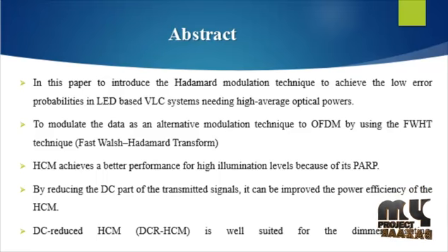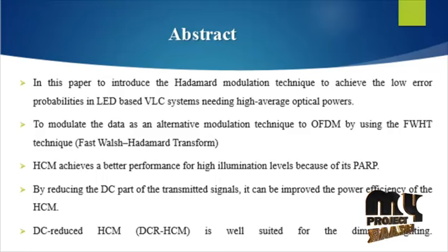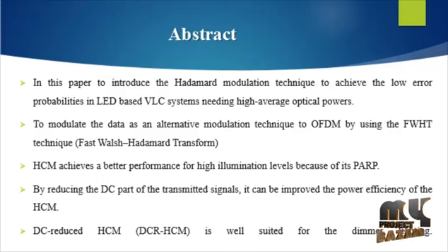Visible light communication refers to the communication technology which utilizes visible light sources as the signal transmitter, the air as the transmission medium, and the appropriate photodiodes as the signal receiving component. Visible light is the form of electromagnetic radiation covering wavelengths from 390 nanometers to 750 nanometers, that is, in the terahertz range of 400 to 800 terahertz. VLC is a subset of optical wireless communication technologies.